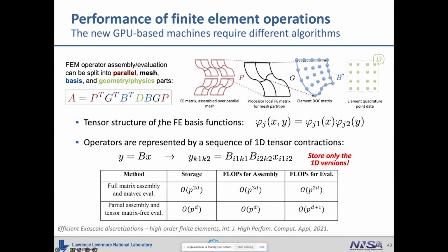Also, can we mix both of these like in adaptive meshing, where we can have both quads and triangles at the same time? If yes, what happens to the complexity in problem solving? We can, yeah, because it's finite elements, you can have a mixed mesh, but it depends what you want to do. If you want to do these fancy performance optimizations, then it's not so good because you have to treat the different cells differently.